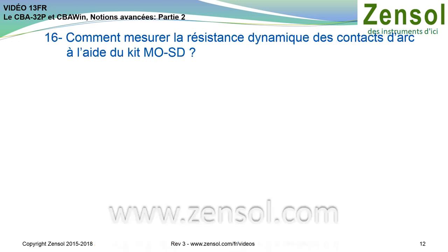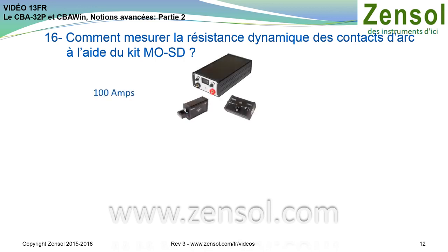How to measure the dynamic resistance of arc contacts using the MOSD kit. Dynamic contact resistance measurement, known by the acronym DRM, is a widely recognized test method to check the status of main and arcing contacts without having to open the circuit breaker. The CBA-32, in conjunction with the MOSD kit, can be used to measure the resistance of any contact as a function of time.